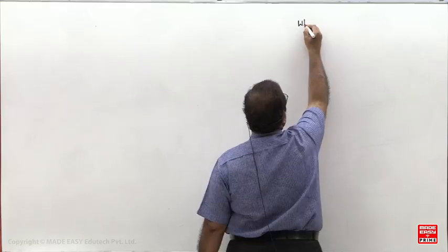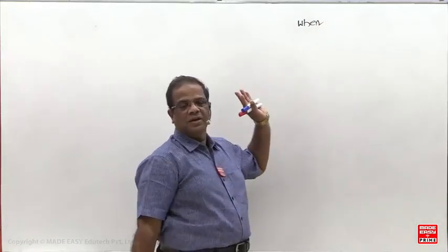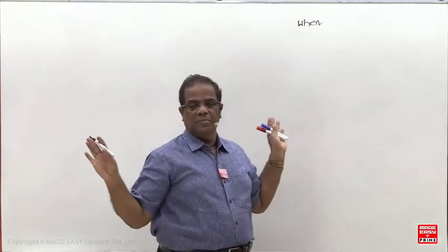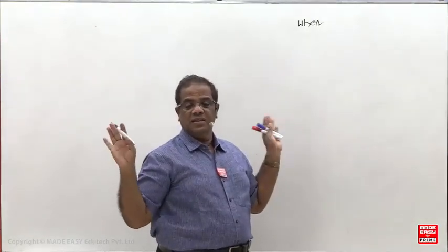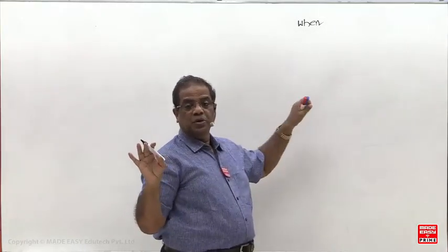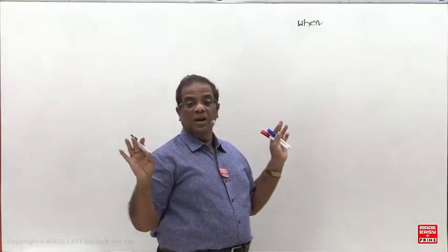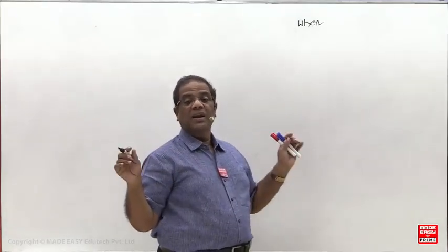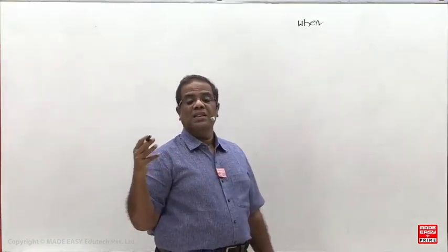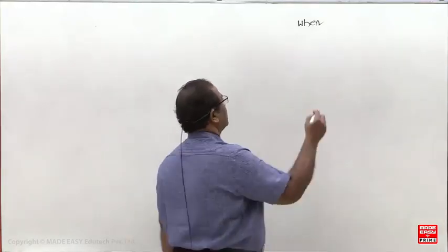From an objective point of view, you can use this method. Whatever I am giving now, from an objective point of view, asks only for the principal stress. Most of the questions ask for the principal stress. So this method should be used only if you ask for the principal stress, not plain locations. It applies if you ask only for principal stresses when axial load, bending moment and twisting moment are acting, that is, if you ask for the maximum tensile, maximum compressive, or maximum shear stress in the member.